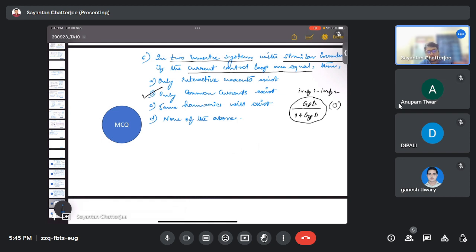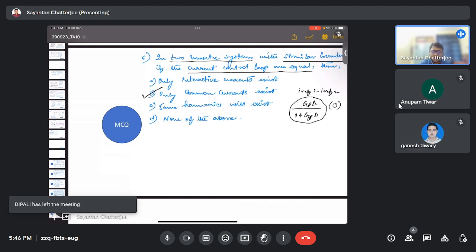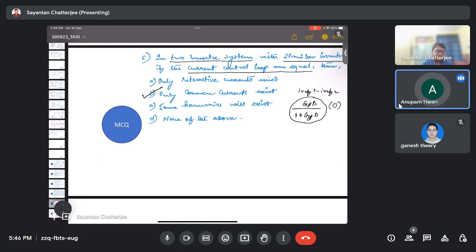In a practical microgrid operational scenario, both of these can't be the same. Both LCL filters can't be the same, because no one can design them with exactly the same parameters. They would try to design them the same, but it can't be the same in a practical operating scenario. So that would inherently lead to some issues, some challenges. Can we say this interactive current is a current which is flowing in the system, not going to the load?